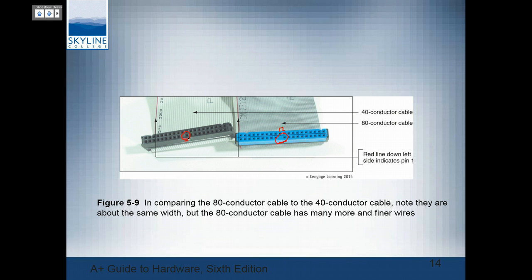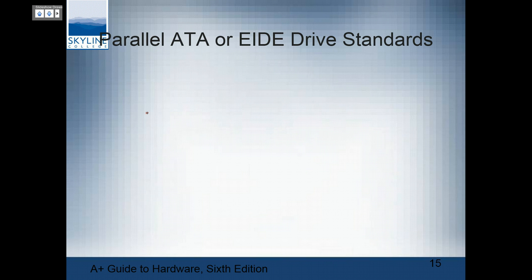If you plug a hard drive in backwards, it's not going to kill it, but it just won't start. The system won't boot. It just kind of sits there. If you plug a floppy drive in backwards, it'll start, but the floppy light will stay on. And this has a red stripe here and a red stripe here. These denote pin 1, and pin 1 should be marked on the motherboard itself, and I think you've seen a lot of those.